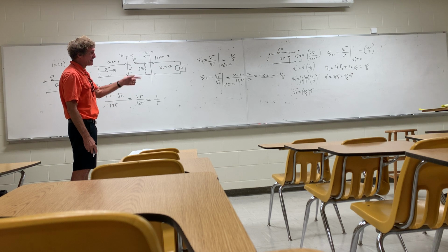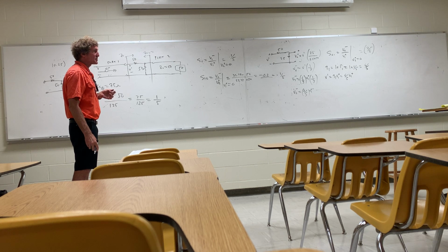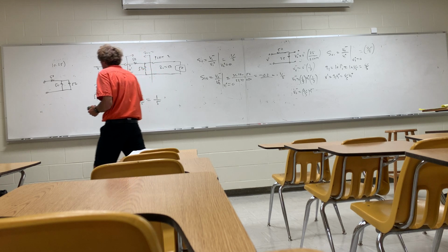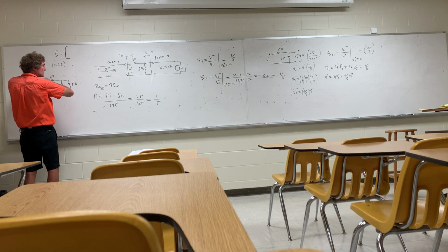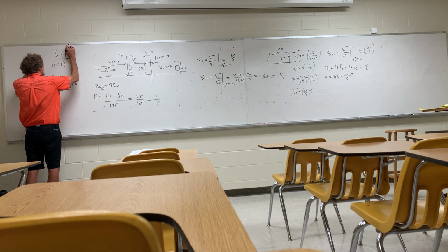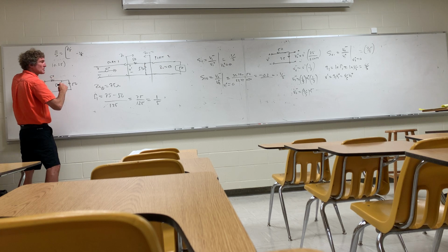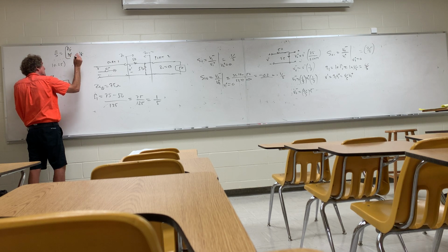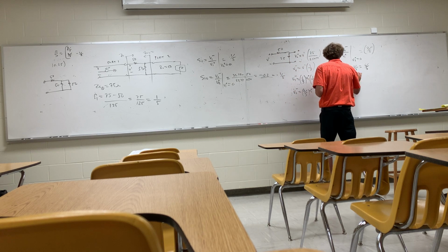All right, anyway, y'all with me on this class so far? So it's 2/5. Let's do the last one we need. Now we've got 2 1s. So as far as the S parameters, let's put them up here. So far for S parameters for this network, we have what? S11 is 1/5, S22 is minus 1/5, correct? And then S21, what did we get for that? 2/5. Finally, we need S12. I'll put it up here and we'll do it.